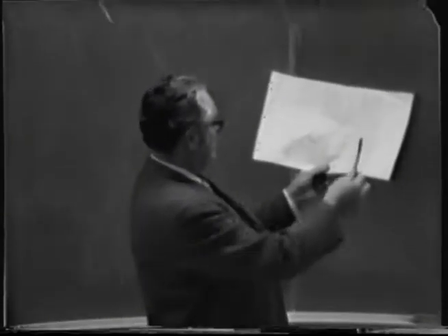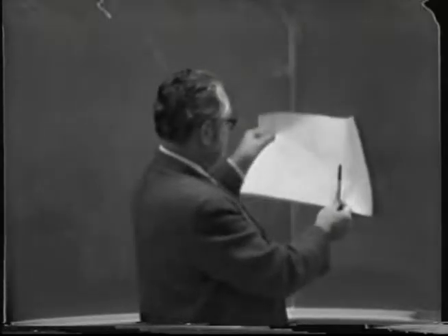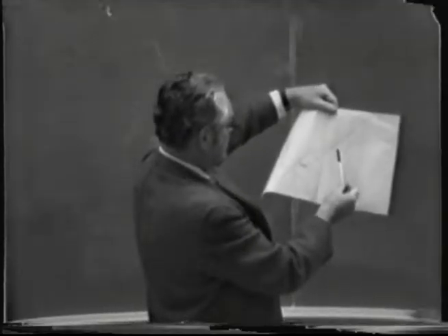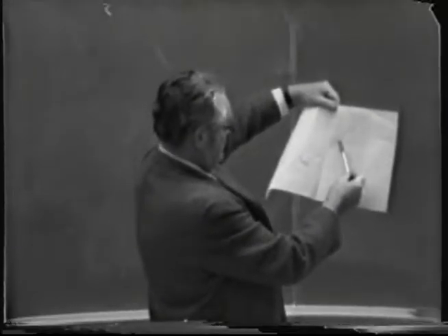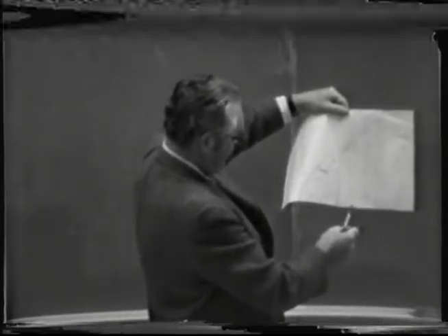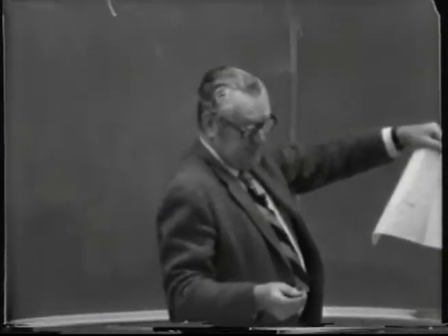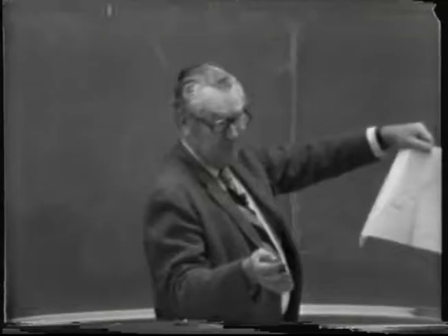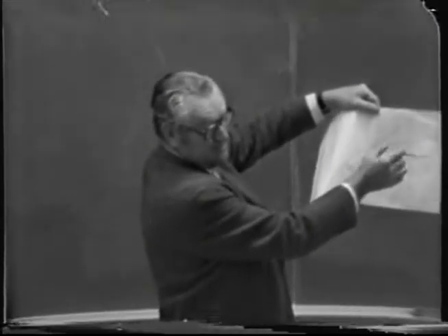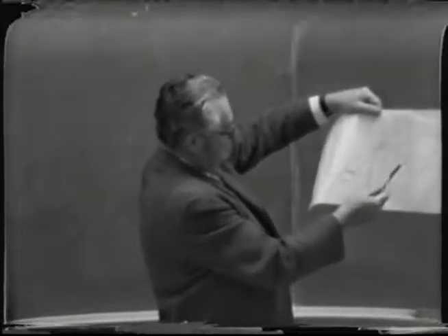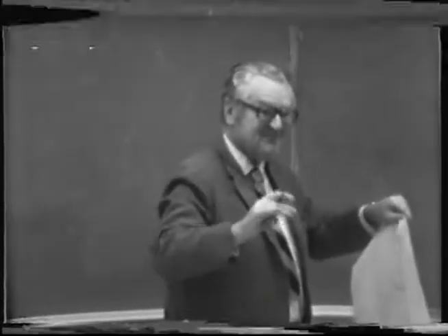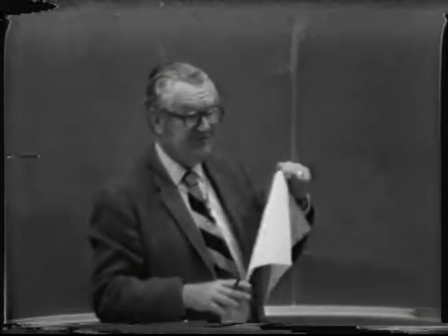But you see, the equilibrium curve becomes tangent here at the azeotrope, which is about roughly 90 mole percent. So right here you see it comes into the tangent of the azeotropic position. And so in reality, you have a little less space to draw steps graphically than you do using the conventional plot.